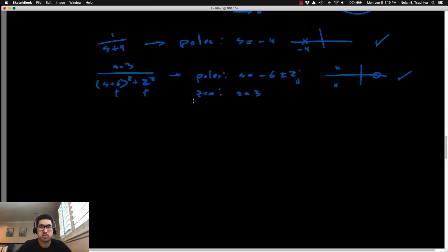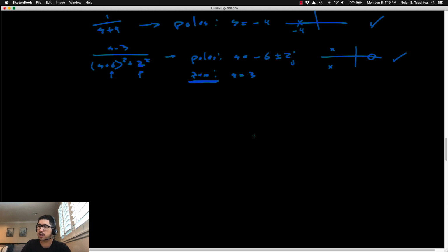It's just the poles. If you want a refresher about how the zeros of a transfer function affect the response of the system, go back and look at the very last 5 or 10 minutes of lecture number 3, and that'll give you a rundown on how these zeros influence the response. But the fact that you have an unstable zero doesn't mean that the system is unstable.